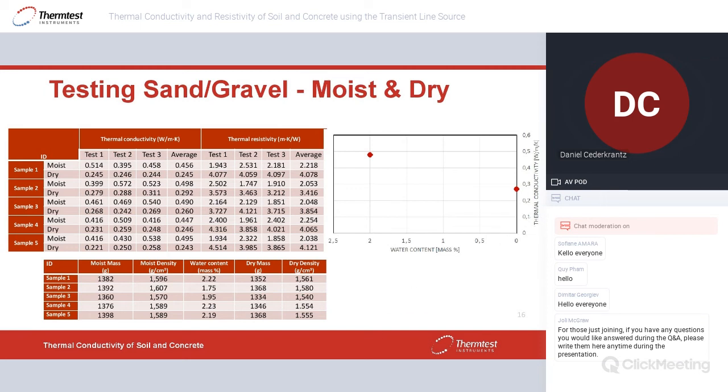So basically, it's quite important to keep an eye on what happens with your cable or with your soil if you want to have control of thermal properties. So if you would bury a cable here, for instance, this might be your normal case, but in a really long, hot and dry summer, the entire soil might dry up, and you might end up down here. So maybe important for any kind of simulation work to make sure that your cables will actually survive this worst case scenario. And this is something that you could call a simple dryout curve.